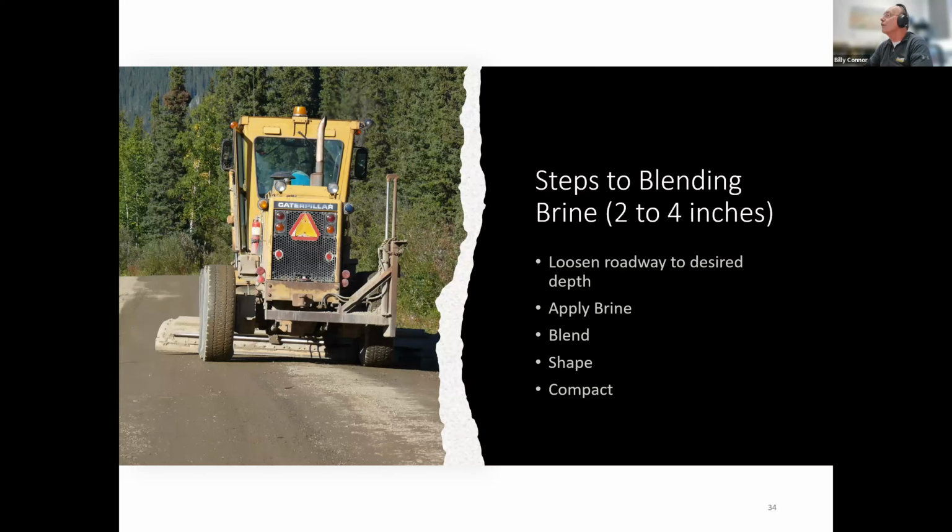Okay, if you're using a water truck, this is the method you're going to use for mixing. For putting in, basically you're just going to dump it into the truck. What I'd like to do is maybe put a foot or so of water in the bottom, add the salt in there, and then add the water to mix it as you go. What you don't want to do is fill it all the way up and try to mix the salt in. Basically, all the salt is going to sit on the bottom for you, and you're going to use the addition of water to help you mix. You don't want to pour it right on the bottom because it makes it a little bit difficult. Put a little bit of water in there so that it doesn't clump up on you. I hope that answers the question.